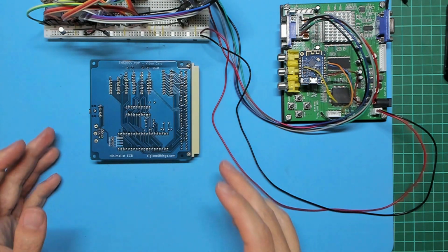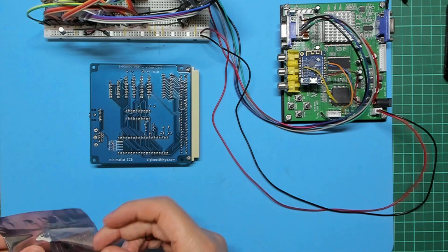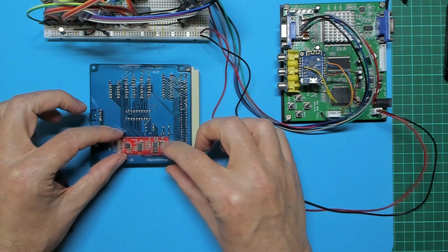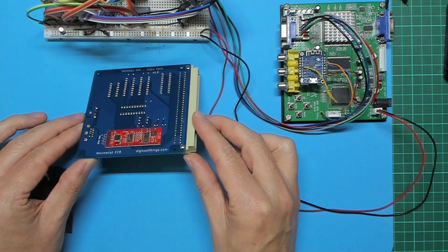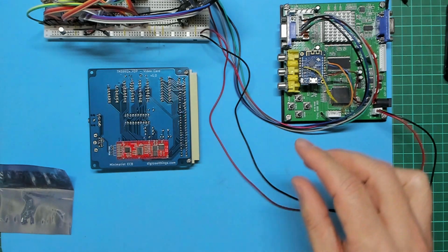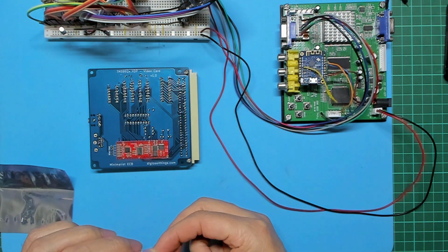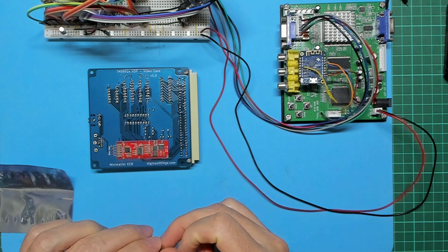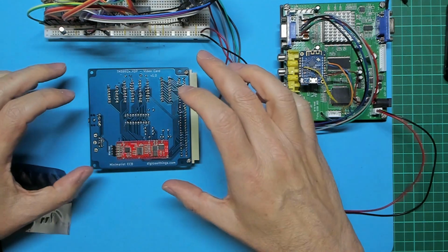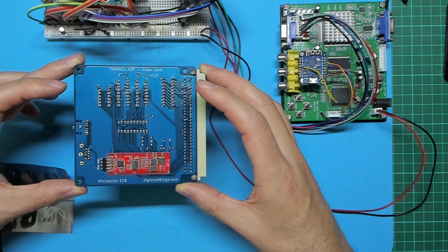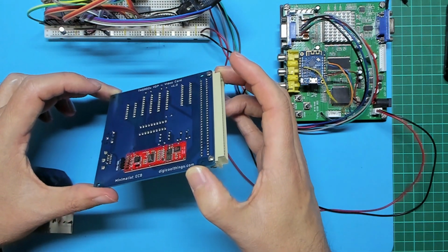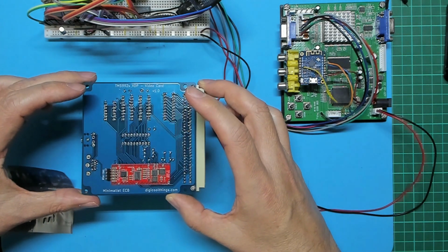So there's the solder side. As you can see, if I grab a TMS module, this simply just drops in place behind the IC socket, and is soldered in place via the relevant connection pins. Then I've implemented a 4-pin right angle PCB header to connect the TMS RGB outputs back to the PCB. So that slots in there. And once the signals are back on the PCB, they are routed to the mini DIN output connector. Hopefully you can see that. So it makes a nice tidy solution for a high quality output from the TMS VDP chip.